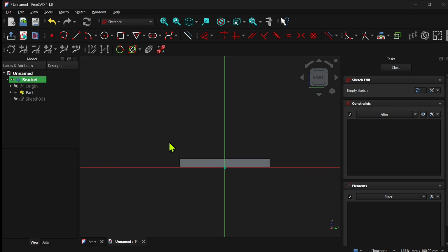So with the new external projection tools, if we keep in defining geometry and use the external projection tool, when we import the line instead of the points, this comes in as solid. We can then use this instead of sketching another line, making our workflow a lot quicker. As you can see, it's still fully constrained. Let's carry on with the line and create the rest of the sketch.